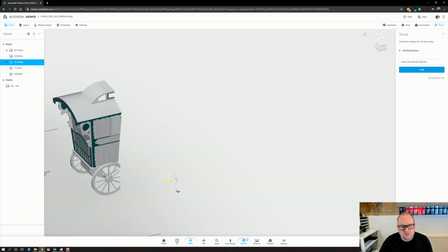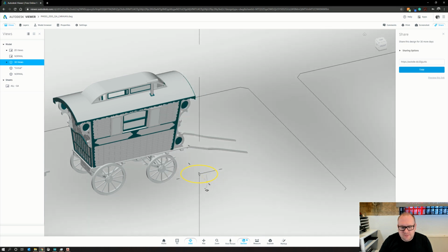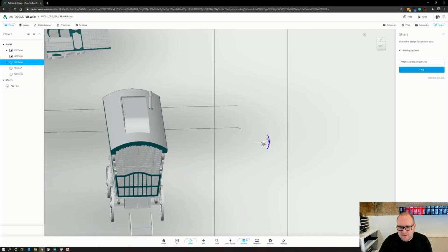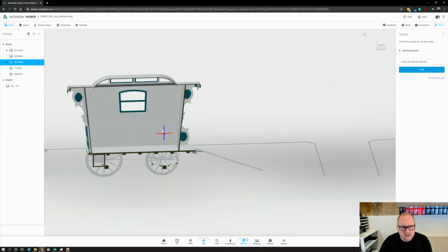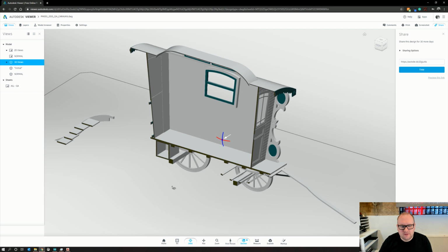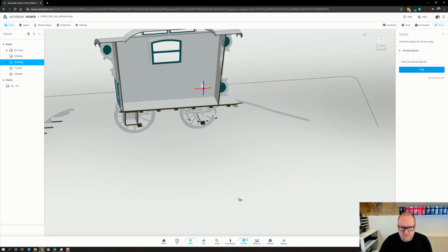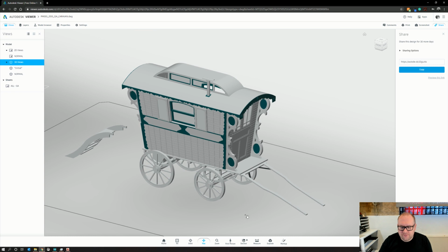And I can scroll through the entire structure any depth I want, and I can do that more or less any angle too. If I now choose to spin the section 90 degrees, you can see how it's automatically clipped. I'm just going to grab that arrow again, and then I'm going to do a section through like so. And then you can see the interior and all the beams and members that we're cutting through. I quite like this tool, it's very useful. To turn that off, we just have to select another tool and then it will turn off.